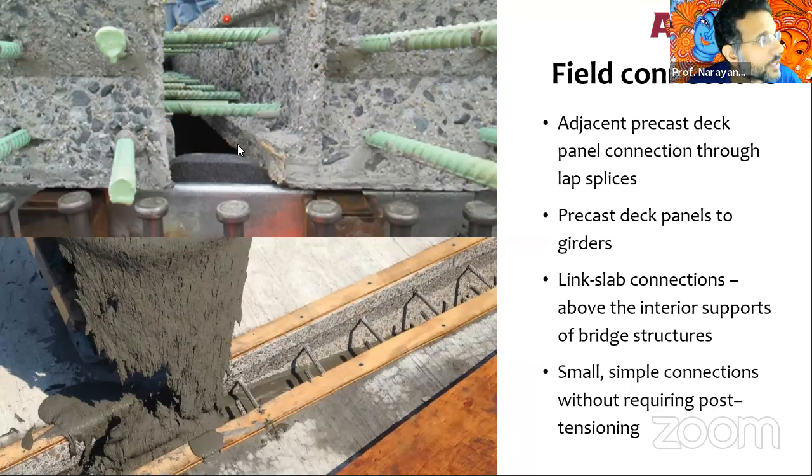So you don't want failure driven by loss of ductility, which is what fatigue does. And you would know that even a ductile material would behave brittle under fatigue behavior, so fatigue loading. So you want to make sure that this has quite a bit of toughness, and also you know that the spacing is not that much. So you need a really flowable concrete that can go in and fill. So now we are coming into two conflicting requirements. You say that I need the concrete to flow, but I need the concrete to be very, very, very strong also.